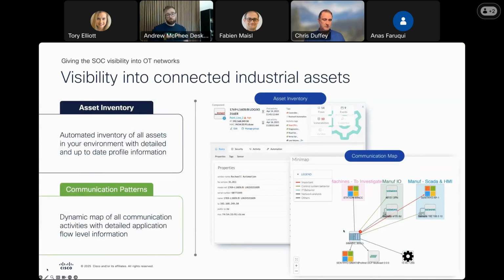And then I just want to show you some screens of what you would get with CyberVision. So what do we mean by deep packet inspection? What do we mean by OT visibility? How is it any different to IT visibility if some of you on this call are new to the OT world? The difference is to do OT visibility, you really need to understand the payloads and the traffic that happens within OT devices. It's not simple net flow where you have IP addresses and open ports. It's actually understanding the payload properties and doing deep packet inspection of OT protocols. So the Modbus, Ethernet IP, Siemens S7, OPC UA, things like that.